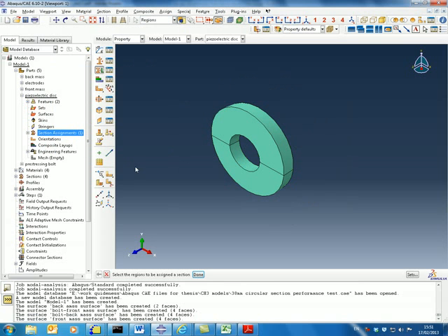And because the piezoelectric disc is an orthotropic material, it's required to define the preferred or axisymmetric axis. In piezoceramic material, we call this the pole direction, where the material will be excited and will respond in this direction. In this model, I'm using the Z direction, or direction number 3, as the pole direction.